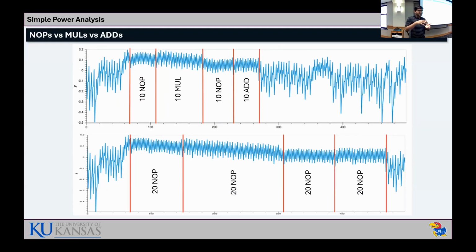It is cumulative, so you cannot localize any ALU operation. You're getting the whole power trace from the CPU. So if it is running other modules also, which are emitting noise randomly, the attacker will not know what's happening here.